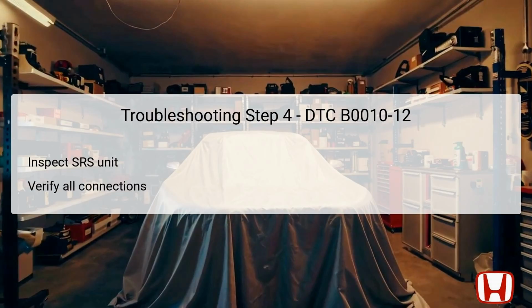DTC. The final troubleshooting step involves a thorough inspection of the SRS unit itself. If previous tests of other components yielded normal results, the SRS unit is likely the source of the problem. Carefully examine the SRS unit connection points and internal circuits for any signs of malfunction or damage. It's essential to ensure that all connections are secure and free from corrosion, which could impede functionality.